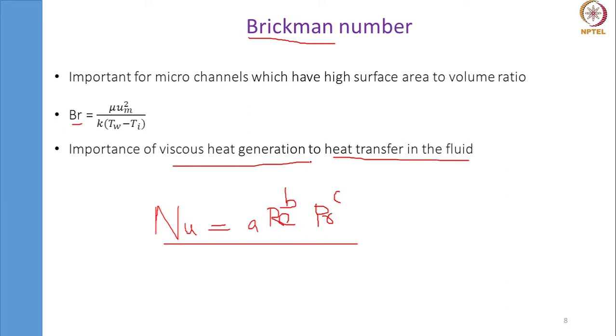However, when the regime is the free molecular regime, the fluid molecules' interaction with each other becomes comparable with the interaction of the fluid with the wall. So we need to consider those interactions also while considering the heat transfer coefficient, that is the ability of the fluid to give away heat quickly or accept heat energy quickly.